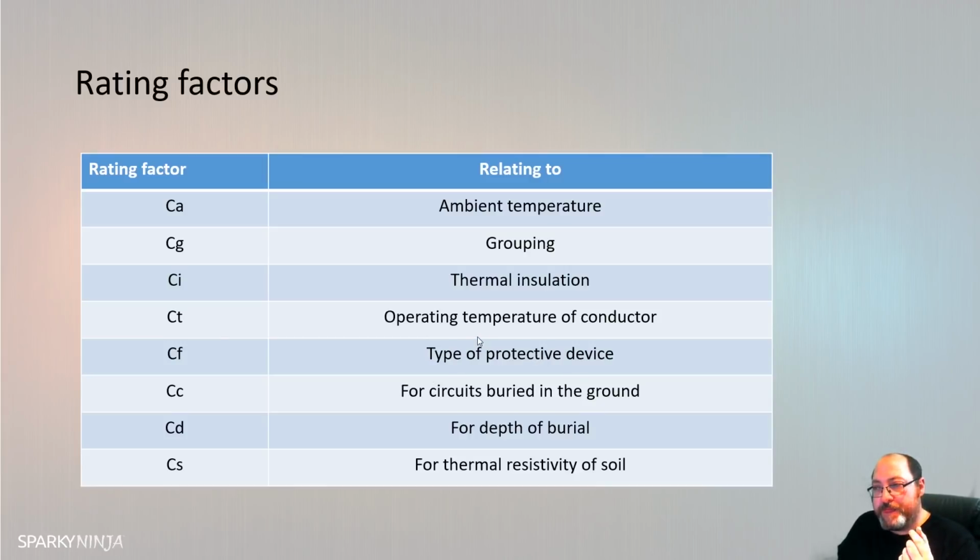When we looked at the overcurrent protective devices, we talked about the BS 3036 protective device in particular. And there was something that said we had to consider the long time it takes to operate under a fault condition, specifically overload. And there was a factor of 0.725 when we covered that. Think back to when we talked about protection against overcurrent, which was Chapter 43, section 433, protection against overload currents.